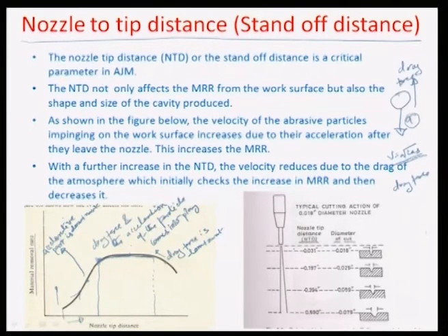Sometimes the practical limitation, particularly of a microsystem or micro device, is that you have to operate at a certain distance from this device, because you are using a mask in the process, and this mask is a hard material with a certain thickness through which the abrasive is being routed. So there are openings or windows in the mask through which the abrasive is routed, and this strikes and removes the material where it makes an impact by creating brittle fracture.